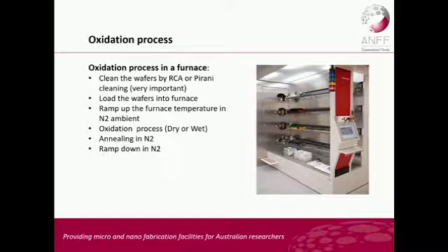I know that in UQ there are probably a few oxidation furnaces around. I don't know whether, when you run the process, you follow this step. Usually after oxidation, you need to anneal the oxide layer at a high temperature because there are some defects. You need to anneal it after you finish the oxidation process.